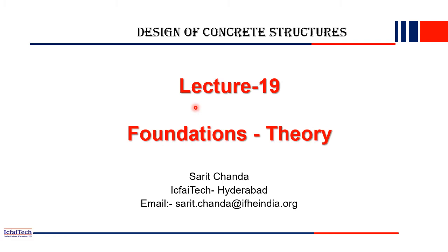So basically what happens, whatever loads are coming from the superstructure, like from the slab to the beam, beam to the column, and ultimately column to the foundation, the load goes. So from the superstructure, load transfers to the substructure, and through the substructure or foundation, the loads are transferred to the nearby soil. So thus, the foundation structure effectively supports the superstructure.